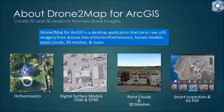Drone2Map allows you to create 4 classes of products. Ortho mosaics, essentially 2D products, which you're somewhat used to, things like your base map imagery. You can also do digital surface models, imagery with height values, that is. You can have point clouds for 3D analysis, and a fourth option, which allows for smart 3D inspection of data. So this is good for bridge inspections, for example, or if you need to assess the surface of a building, the structure itself.